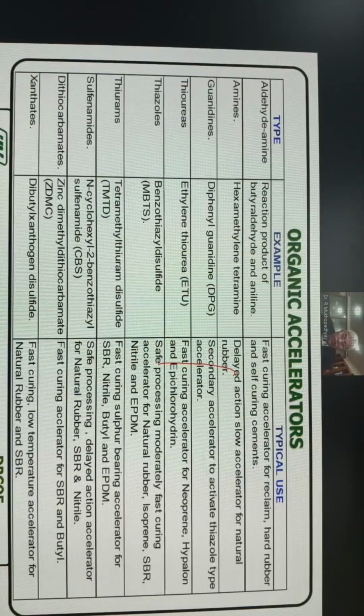This I already explained to you. Then the different types of accelerator, what is the curing temperature. Sometimes with the accelerator, you have primary and secondary accelerators or synergists you have to consider. For boosting, you have slow, medium slow, fast, medium fast, and ultra fast, depending on the curing temperature, whether you use room temperature or you go for high temperature curing.